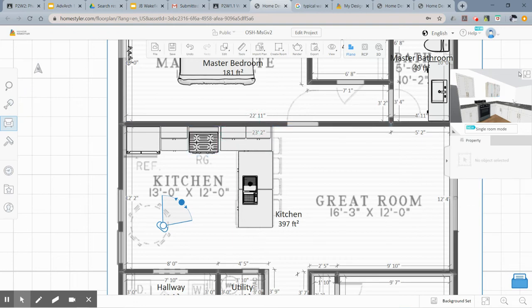And now you can see, oh, one last thing, sorry. I'm gonna Control-C and V another countertop into here. Now, that's too high to be above the stove. That wouldn't meet fire code regulations because what's on your stove might cause a fire on the cabinet above. So what you're going to need to do is change the height of it and the lift.